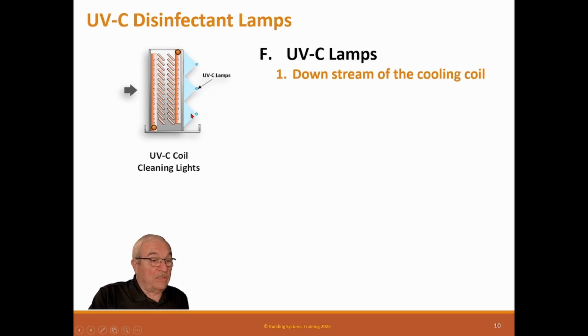They will disinfect. Now, during COVID, we researched a lot to see if these could be used to kill the bacteria. And they will, but the problem was there's not enough dwell time here. You would have to have several sets, and the dwell time needs to be 10 or 15 seconds, which isn't working here. This air is moving down the road. So they do keep a coil clean, and they're very good. They pay for themselves in energy just by keeping a coil clean.